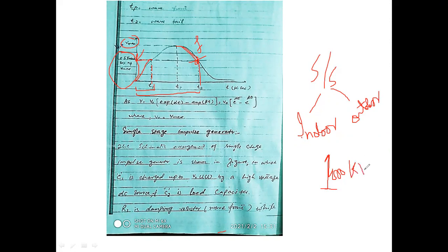This is the value for the lightning voltage, and it may be more than this, as every stroke may inject lightning current up to about 100 kiloamperes, and even more in the transmission line. Each stroke is then followed by traveling waves, whose magnitude is often limited by the maximum insulation strength of the overhead transmission line. The rate of voltage rise of such traveling waves is at its origin directly proportional to the steepness of the lightning current.